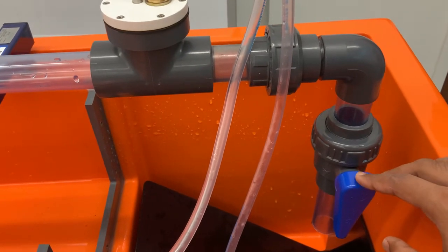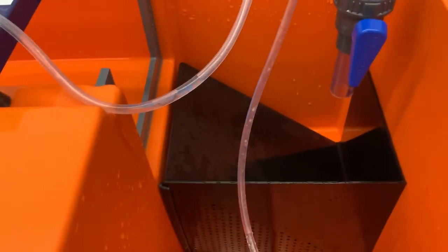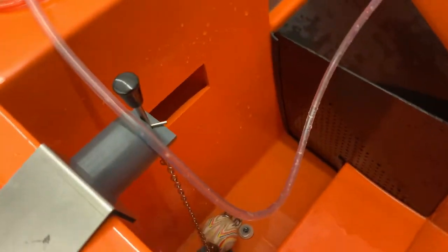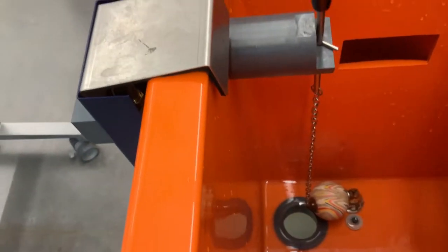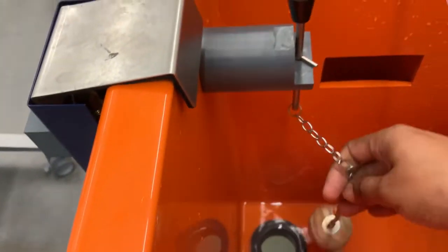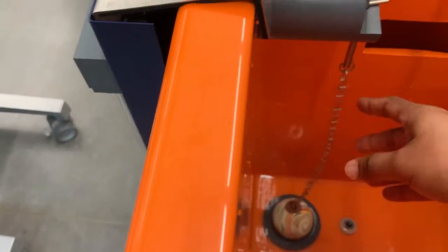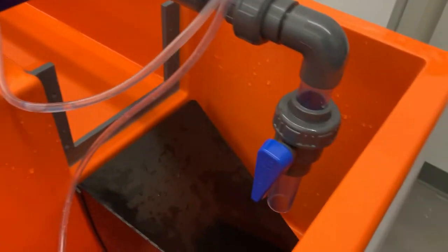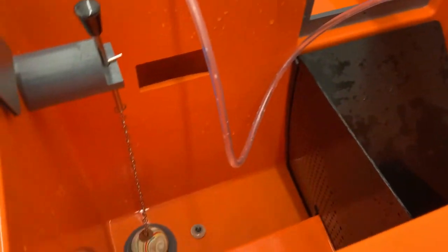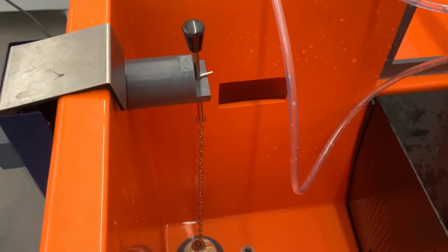We can close this valve to see only static pressure, and this is the reservoir I was talking about. If we close the O-ring down there using this placing right there, then I'll be storing the water that is coming through the system, and I can measure the volume and divide it by the time and get the flow rate to compare with the Pitot tube value.